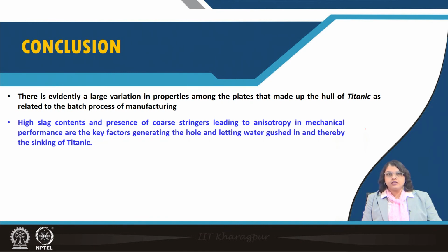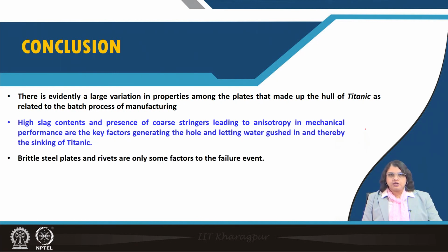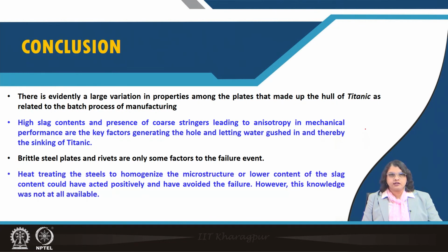High slag contents and the presence of coarse stringers leading to anisotropy in mechanical performance are the key factors generating the hole and letting water gush in, and thereby the sinking of Titanic. And brittle steel plates and rivets are some factors for the failure event.